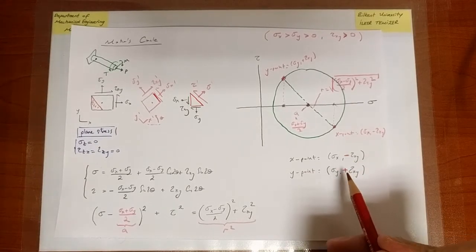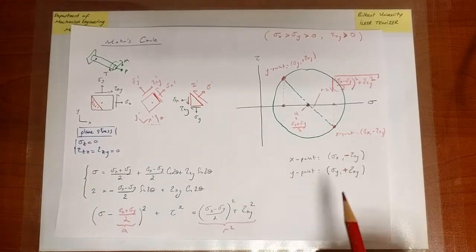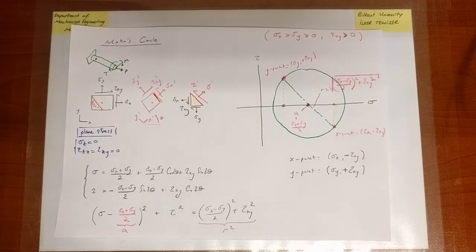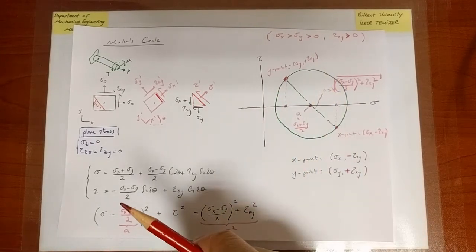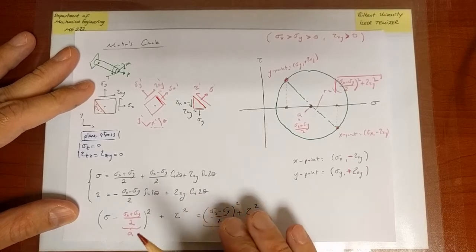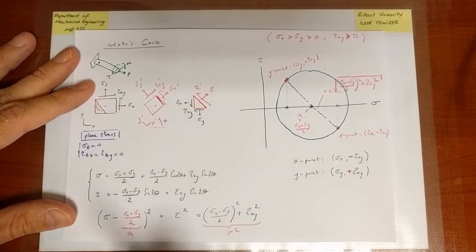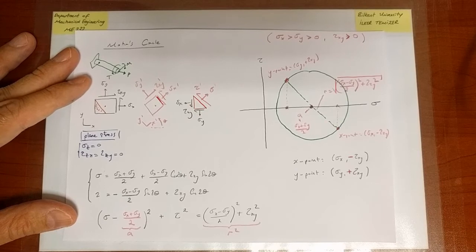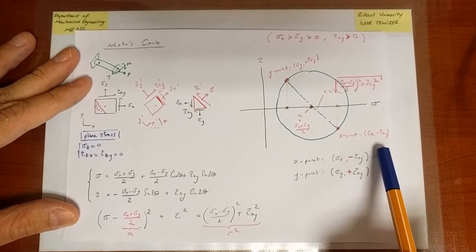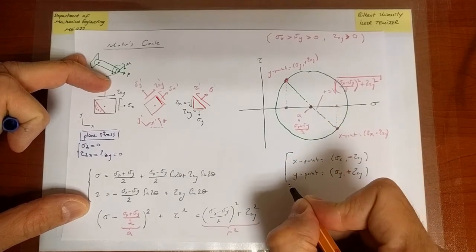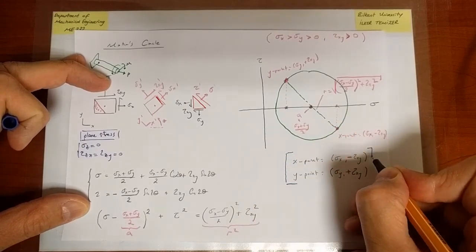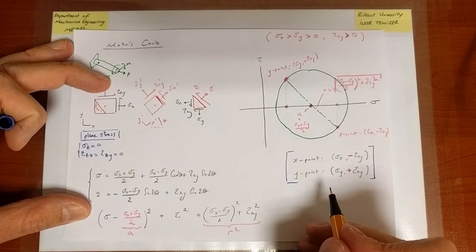Okay, for the sake of being complete, I put a plus here. Of course, it is obsolete, but I put it there anyway to distinguish these two choices from each other. Okay, right. That's our Mohr circle now. So actually, the way we draw the Mohr circle is not exactly in this order. The way I would normally draw it is, first, I would always know that this is the most important piece of information that I should keep in mind: where to put the points, and everything else follows from that.